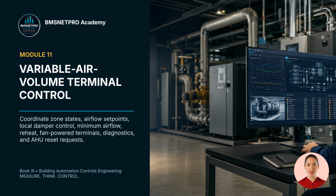Welcome to Module 11, Variable Air Volume Terminal Control. A VAV terminal is not simply a damper with a room sensor. It is a coordinated airflow and temperature system that must serve comfort, ventilation, pressure, noise, and equipment limits. In this module, we will coordinate zone states, airflow set points, the local damper loop, minimum airflow, reheat, fan-powered terminals, diagnostics, and AHU reset requests. The goal is to understand how one terminal affects the room and also the larger air handling system.